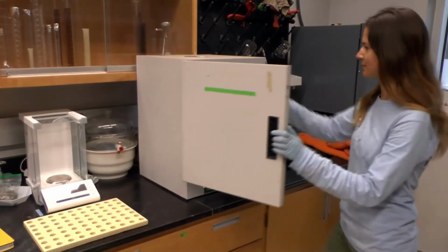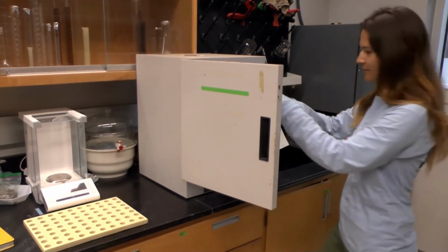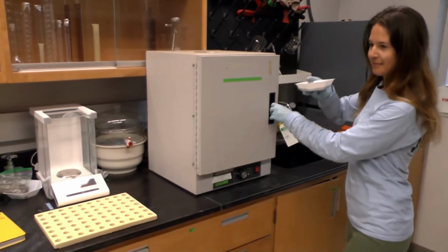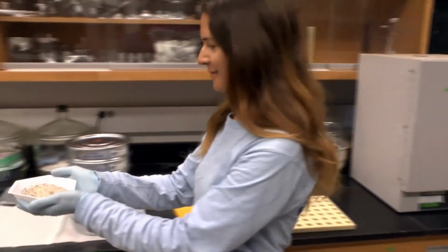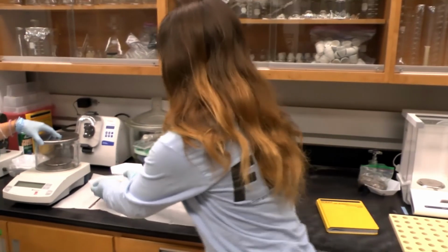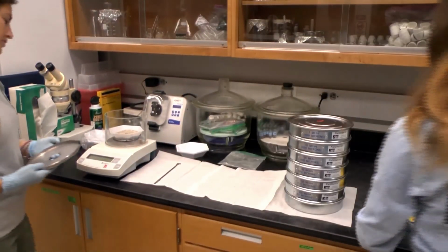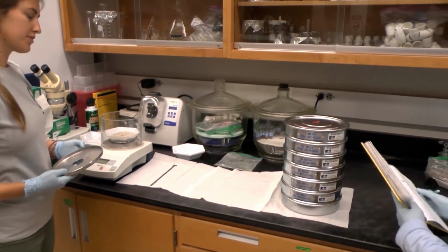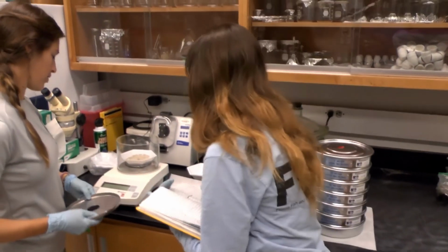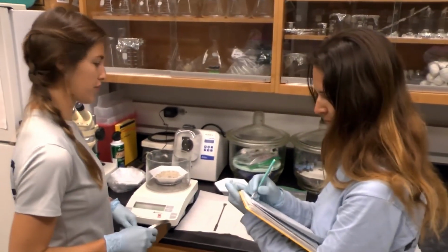Put the remainder of the surface sediment sample in a weigh boat and dry the sediment at 105 degrees Celsius for 1 to 4 days before putting it in the sieves. Record the weight of the sediments throughout the drying process. The sample is dry when it retains a constant weight and is therefore no longer losing water to evaporation.